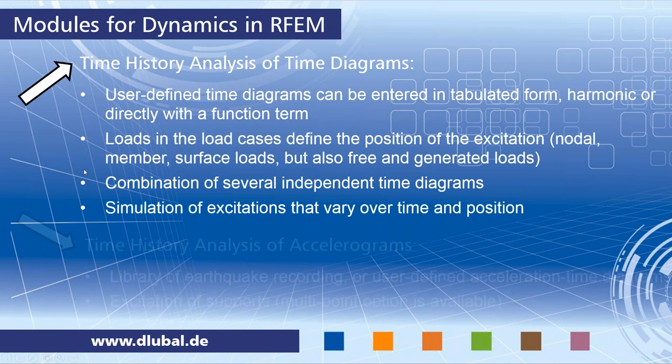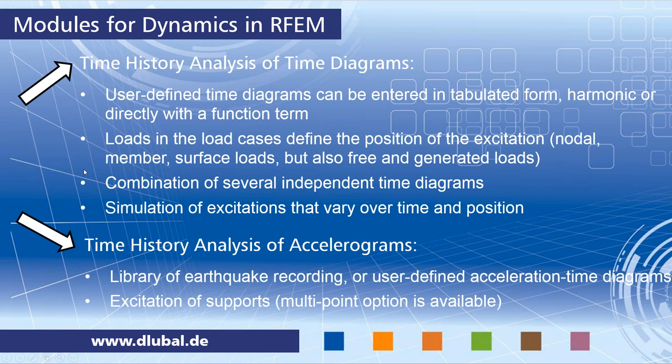The second option we have available is a time history analysis of oscillograms. You can either choose an earthquake recording from our library, or you can define the acceleration time diagram yourself, or import it from Excel. Here you have an excitation of supports. So this is not a free excitation somewhere in the structure. It is an excitation of supports, but we have the multi-point option available. This is similar to the response spectrum analysis.